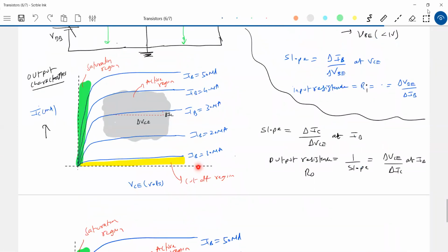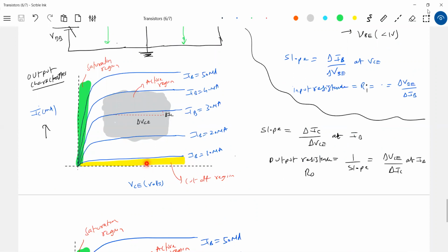So what I do is go for half of it. So what is IC saturation? Suppose it is 10 milliampere. I'll operate at 5 milliampere. That's the best region where I can use it as an amplifier. How to identify the active region? Somewhere nearby half of IC saturation and half of VC cutoff, the maximum, which means breakdown. Suppose 20 volt is there. So you keep operating the transistor somewhere in this region, at 10 volt VC.